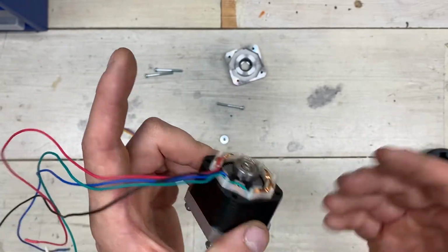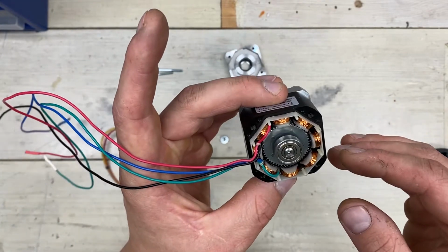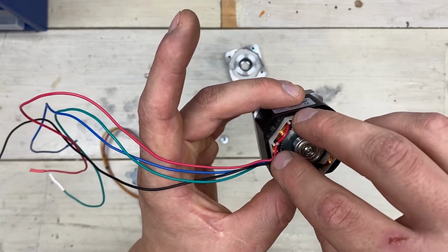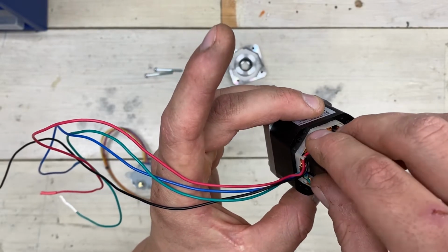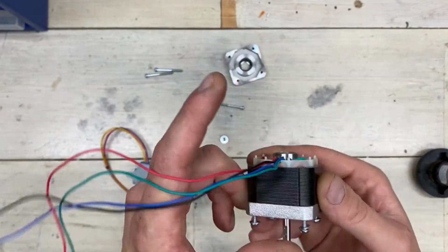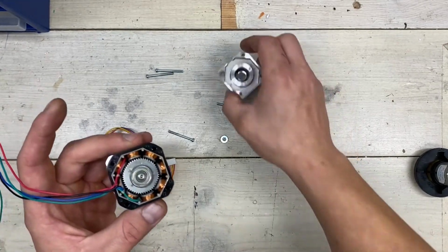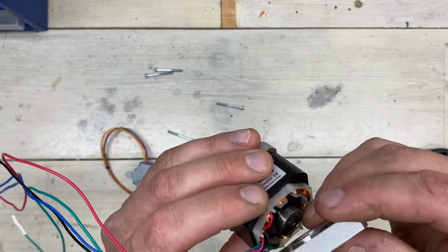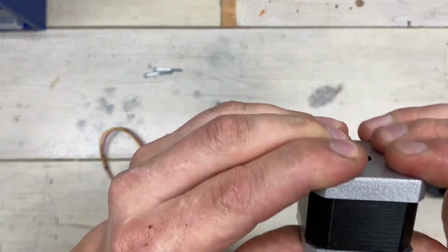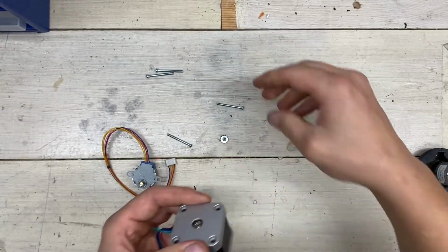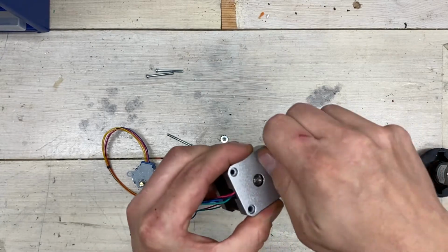There's also something called half-stepping or micro-stepping, where you don't energize the coils fully, but only slightly, so you can get the rotor to move just a fraction of a full step. And being able to move the motor one step or a partial step at a time is of course what makes them extremely useful for home-built machines and home-built CNC routers.